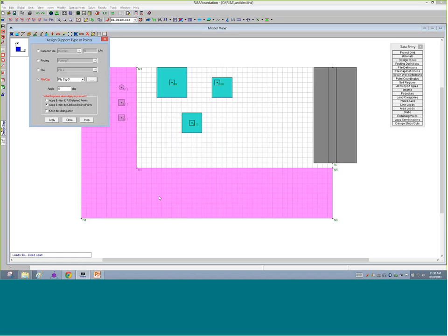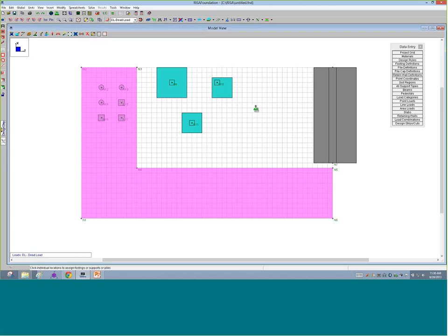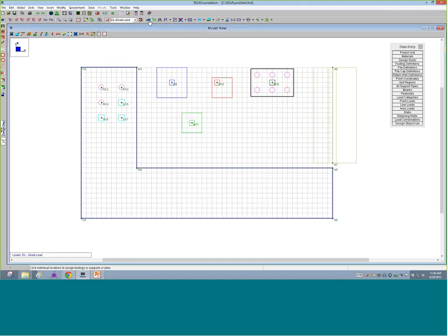So you set all these up and you can just say okay, and you can start drawing this just like we drew a footing. It's a single node. So if I pop that in there, you can see it's a single node. That would be where you'd apply your point load on that single node location. If we look at this in wireframe view, we see those 6 piles that we had underneath that.